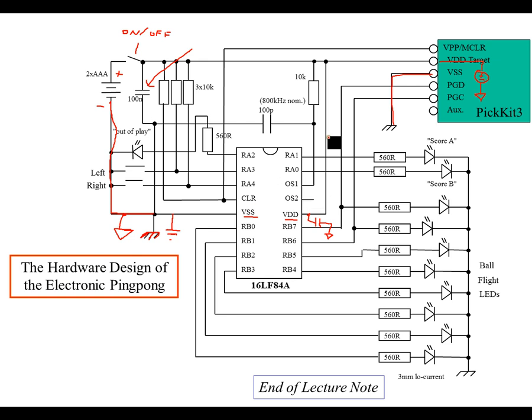In this case, you can see that the OSC1 signal is going to a resistor and a capacitor. So it's a pretty good bet that they're using the RC oscillator inside of this design. If they were using a crystal, then you would have a crystal here, and you would have two capacitors, configured like this. Okay, and this side here would go to ground. This side would go to ground. Okay, but in this case, we're not really doing that.